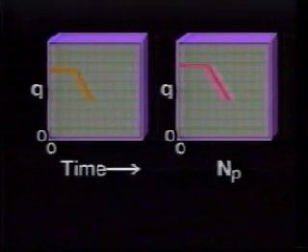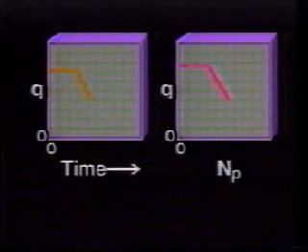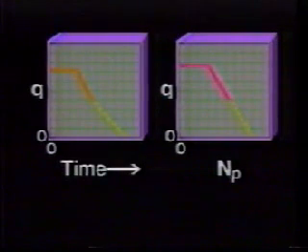Production rate is by far the most popular dependent variable used in projecting future performance. It has the advantage of being readily available and easily recorded. When no major changes in operating procedures are made and no stimulation treatments are applied, the rate curves normally show a fairly smooth declining trend over extended periods. This trend lends itself to extrapolation. This smoothness of decline is one important requirement for extrapolation.